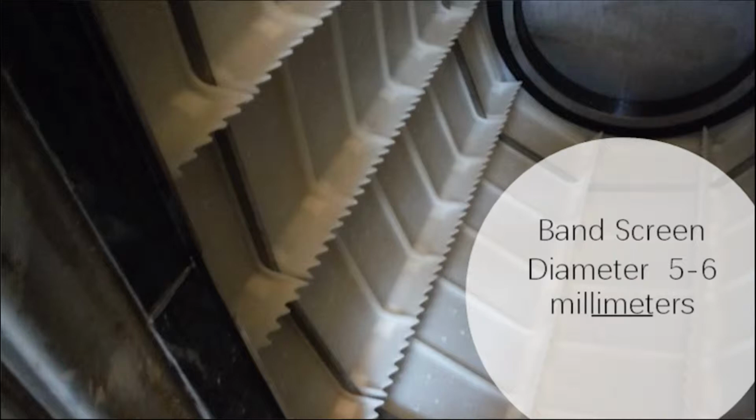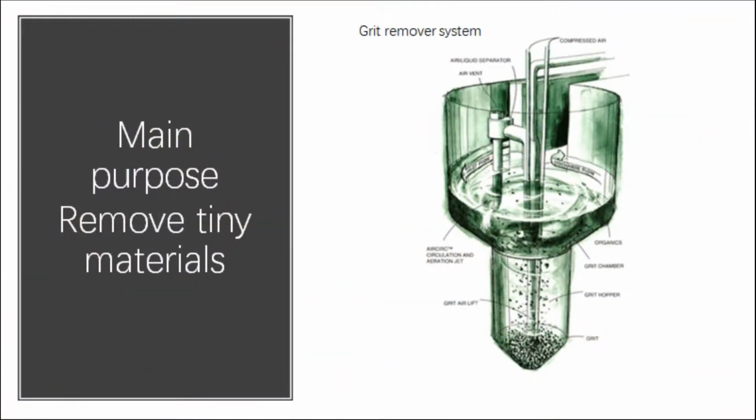After that, the sewage will enter the second part of the inlet work system, which is the grit removal system. According to the survey, 15% of the inorganic materials contained in domestic sewage are small materials with a diameter less than 250 microns, which cannot be removed in the band screen. So, the purpose of the grit removal system is to remove these tiny materials. This system makes tiny grit settle to the bottom of the system through high-speed rotation.